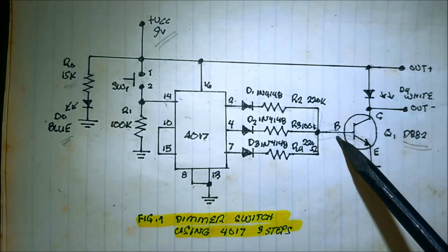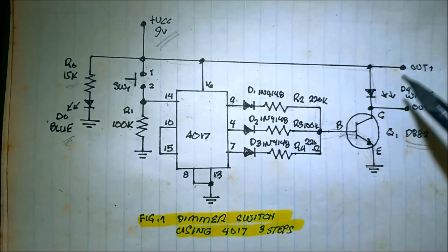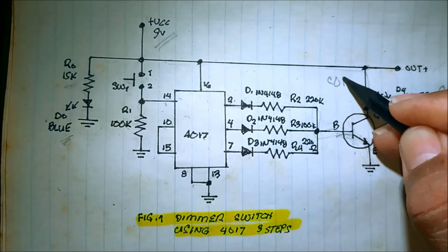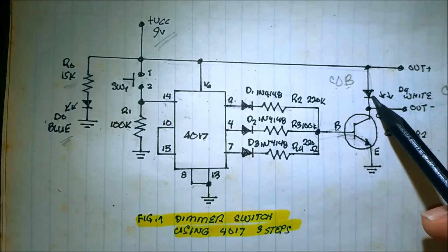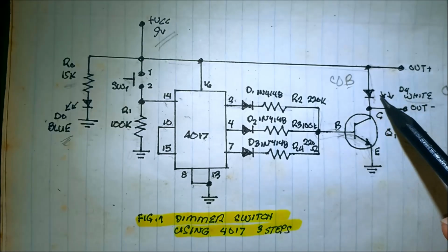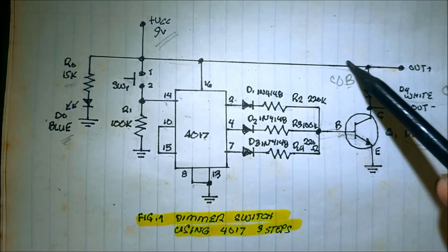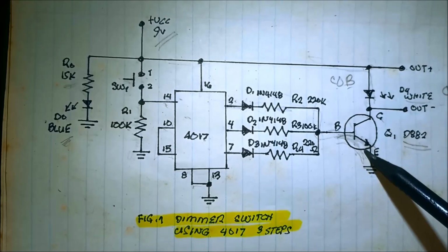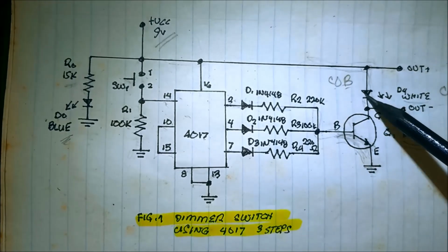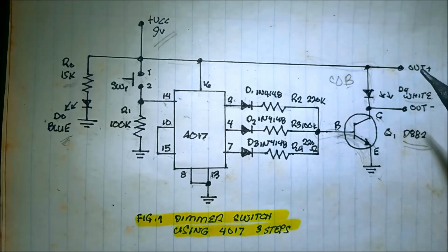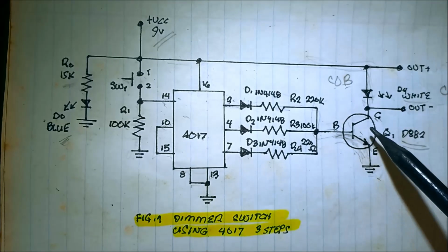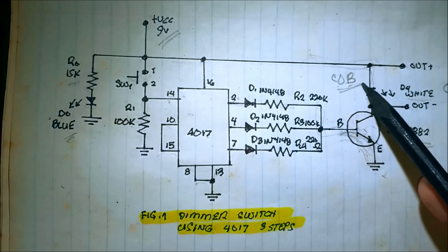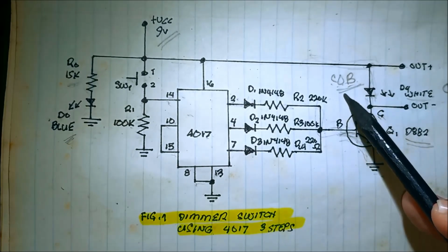Because the transistor switches on, current now flows into the LED. This is the COB, chip on board LED, color white. That is the LED we use. Current flows into the LED, to the collector, to the emitter, then to the ground, because the transistor is now switched on. So the purpose of the transistor is as a switch, also as a driver to the COB chip on board LED. Let us see that.